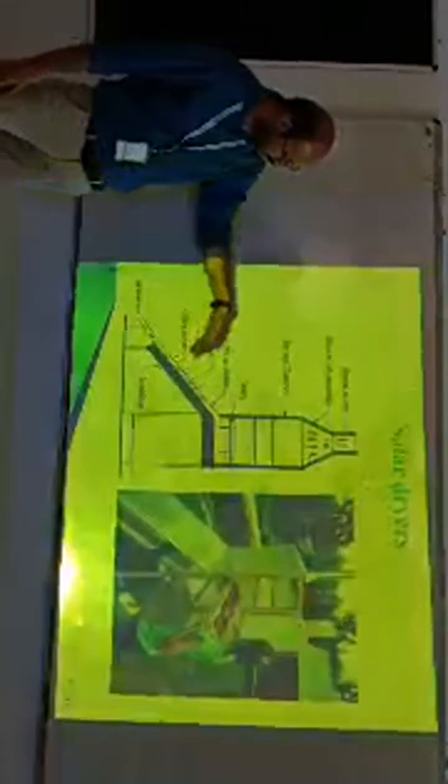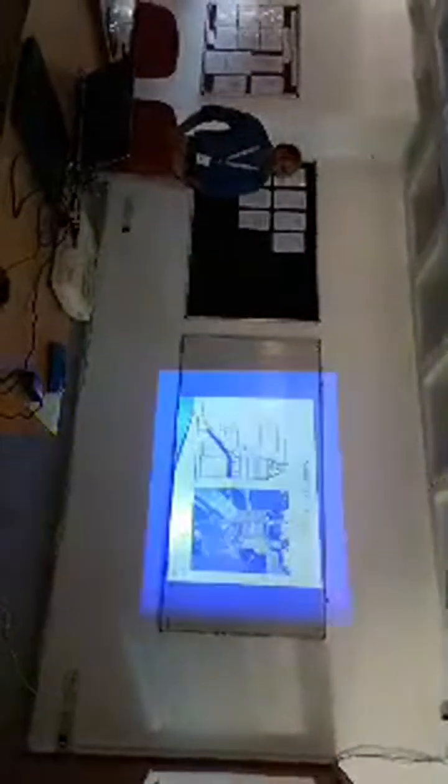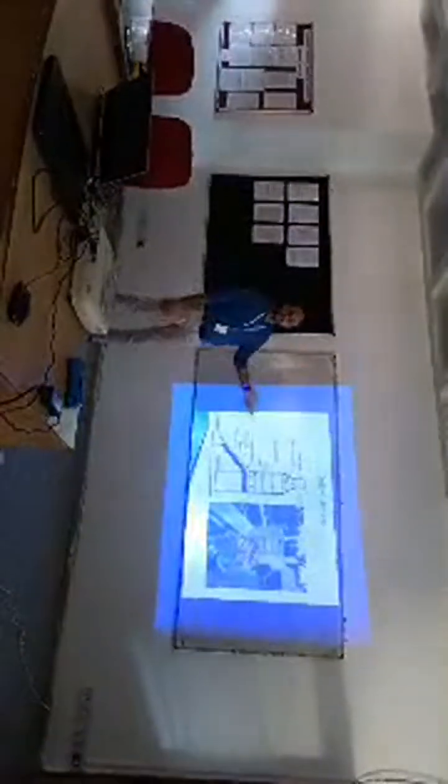This solar dryer is a very simple design to dry your crops or some vegetables. It's a kind of air collector. The solar radiation falling on the glazed surface will be transmitted towards this blackened plate. It gets absorbed. Here the difference is that in the previous design we used the flat plate collector to heat up the water, and now the water fluid is replaced by air.